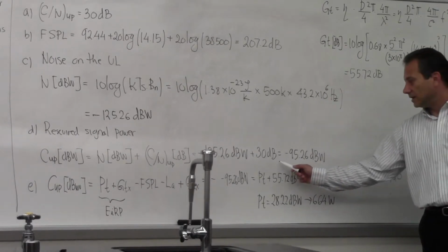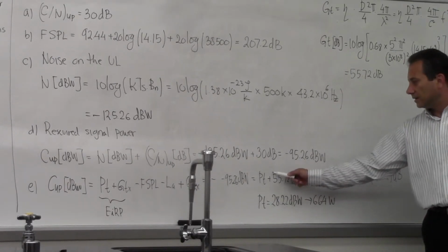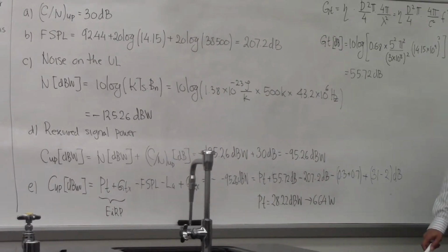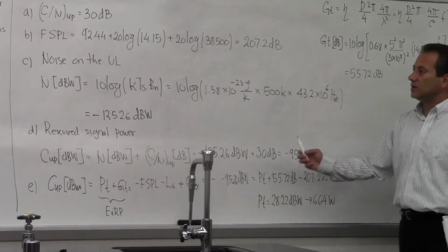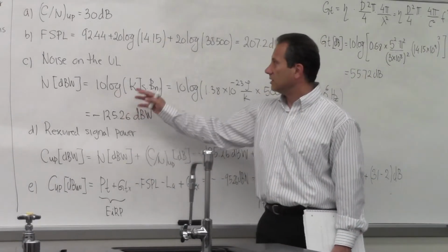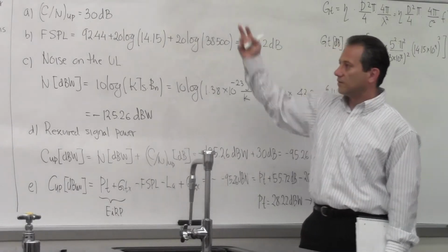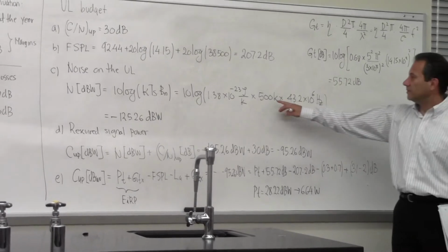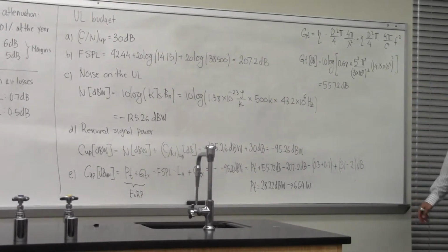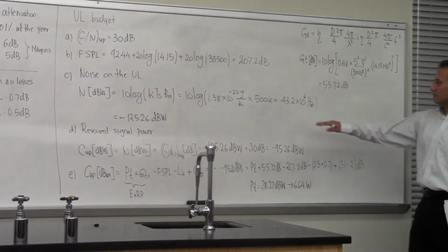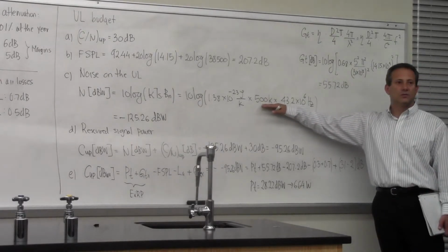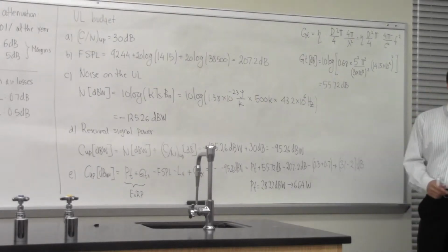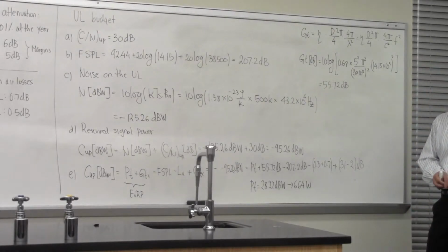The only thing that you can work on to impact the link budget is the size of your antenna, or if you're in an early stage design, maybe you can work on reducing the noise figure of your front end amplifier, because this 500 Kelvin may be reduced by some amount, because only about 300 is the contribution that comes through the antenna, and the rest is the contribution from the front end amplifier.